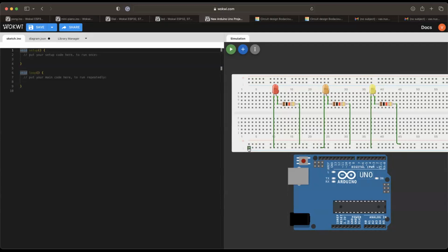That's why you need wires now. So connect the ground to ground, which is right here, and then the positive side, let's connect it to digital pin 2. We're going to change the wiring again, but now we can go to the coding.